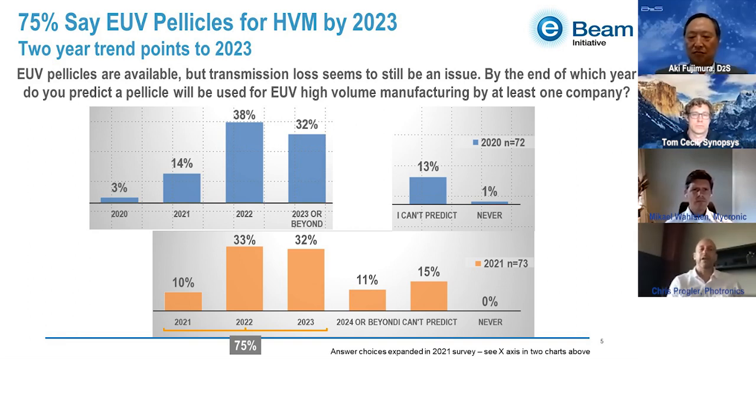It is a lot more hand-holding, multi-start masks, and a lot more inspections embedded into the flow. There are certainly not as many designs, so it's a little more manageable, and there are a lot more cleans. So EUV is partially working because it's still in somewhat of an engineering mode, even though it's in a limited number of chips for mass production.